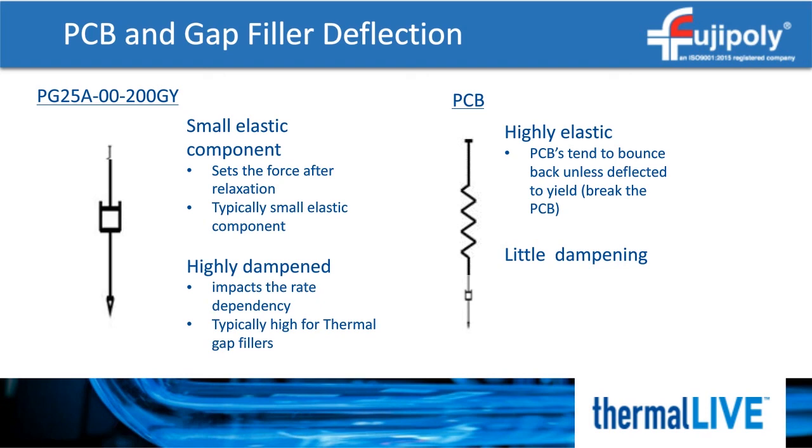Unfortunately, the compression characteristics of a gap filler can be a little complicated. Thermal gap fillers are polymers that are highly loaded with fillers. The movement of the fillers, along with the viscoelastic and viscoplastic behaviors of the polymer, make them difficult to model accurately. In some cases, though, generalizing them as a simple spring and dashpot is usually good enough to get a good understanding. So if we look at the components of our PCB and gap filler stack-up, we see that they